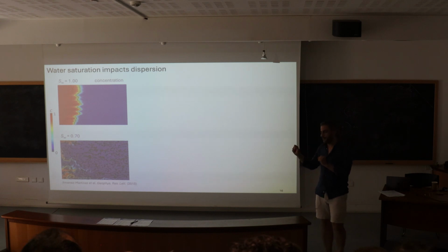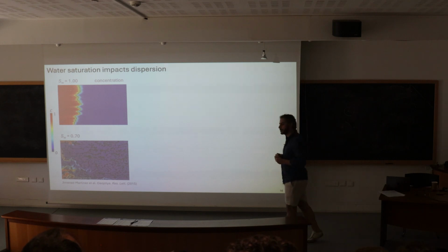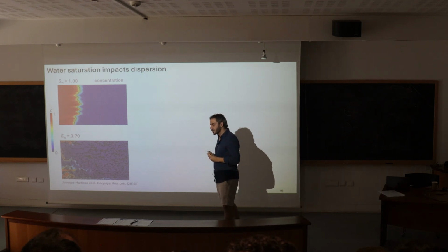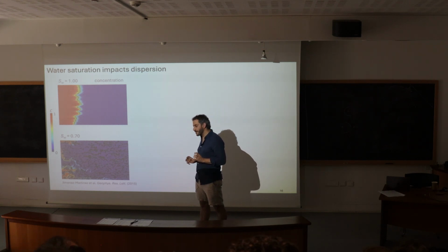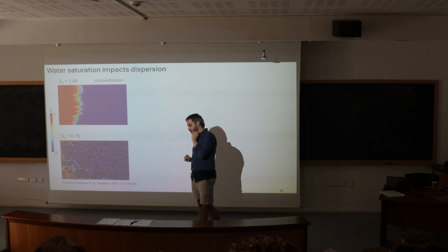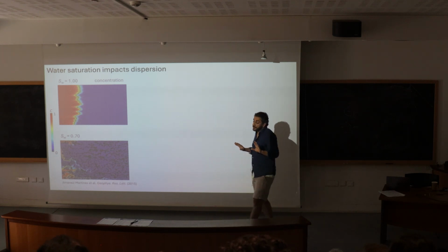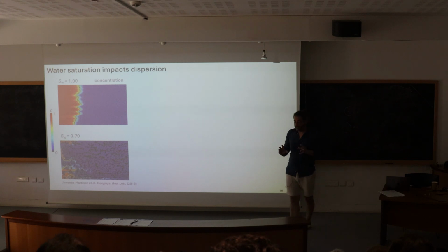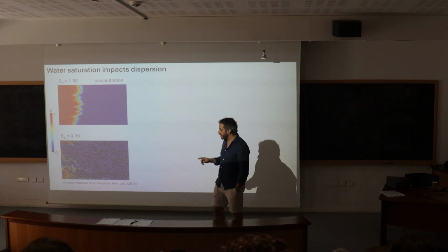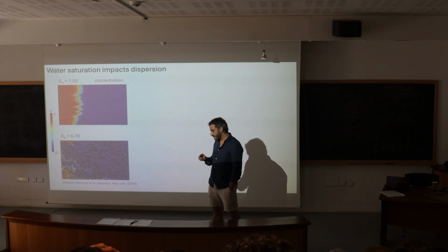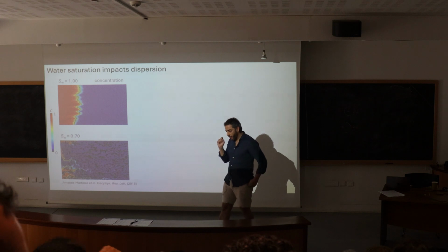Yeah, but you can have internal recirculation in your droplet, some internal fluid recirculation due to shear stress at the interface. We are not moving the interface. Yeah, it's not moving. But I mean, speaking of the no slip versus slip, there are three manuscripts where the PDF of velocities is almost not impacted, and we have done it also for transport, mixing and reactions with the slip and no slip, and the differences are almost negligible.